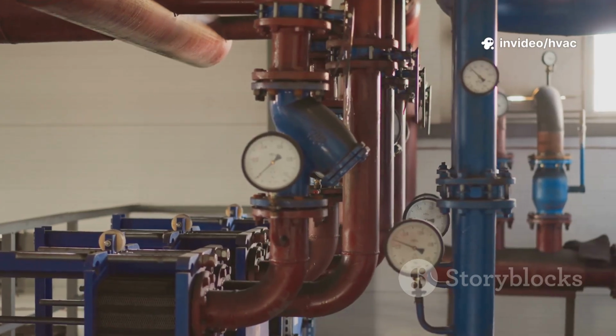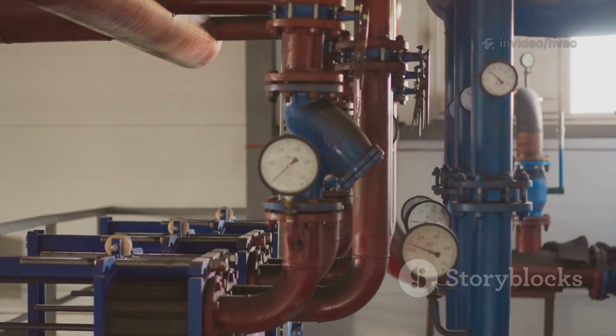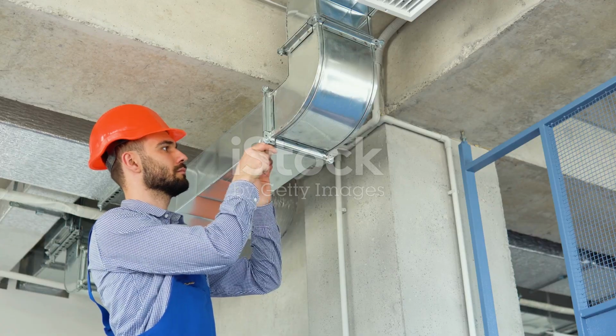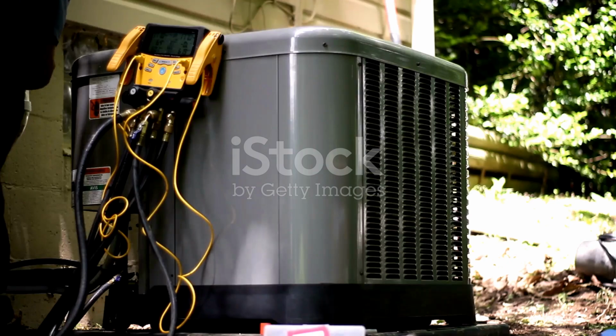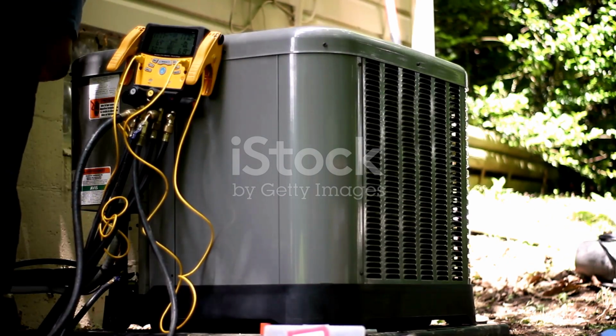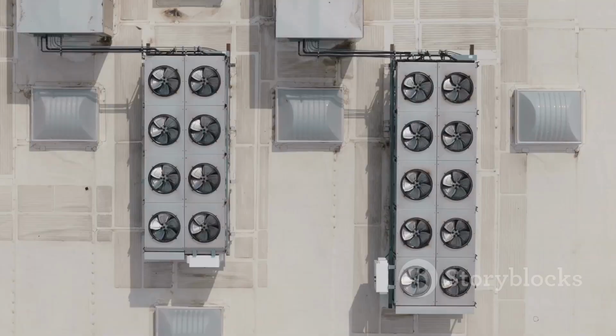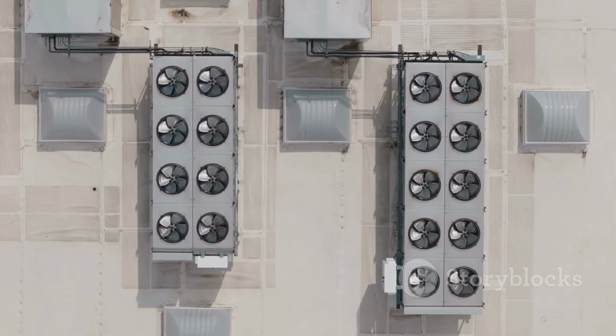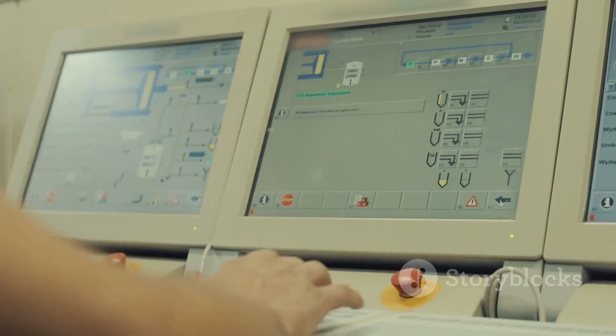Use capillary clips, 2 for the first foot, 1 for each additional foot. Space clips evenly and secure bends. If you lack info, measure directly or use a longer sensor. Avoid shortcuts. Quality matters. By following these steps, you're building a reliable, efficient system. The BMS depends on your attention to detail. That's how you make it right.